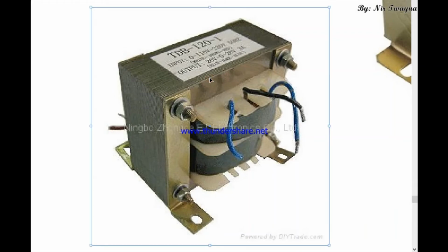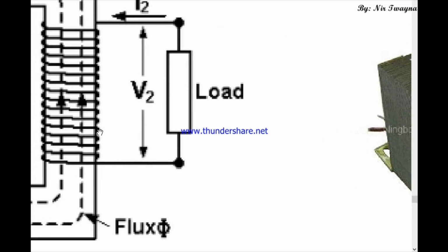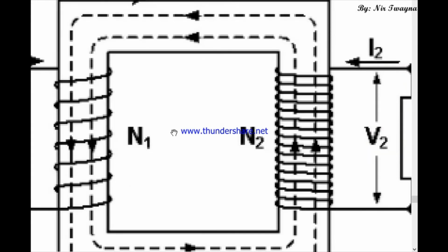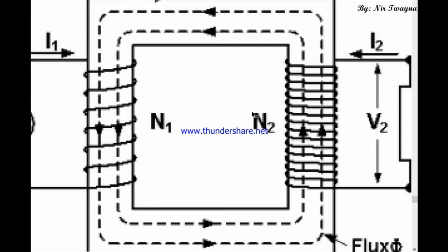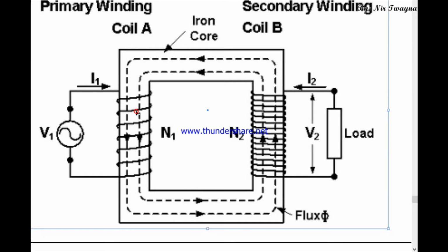Eddy current occurs. Eddy current means, see in this simplified diagram once again. This coil becomes an electromagnet because of AC, and under the influence of the alternating polarity of this magnet, EMF is generated in this coil. But the same can be said for this solid core as well.